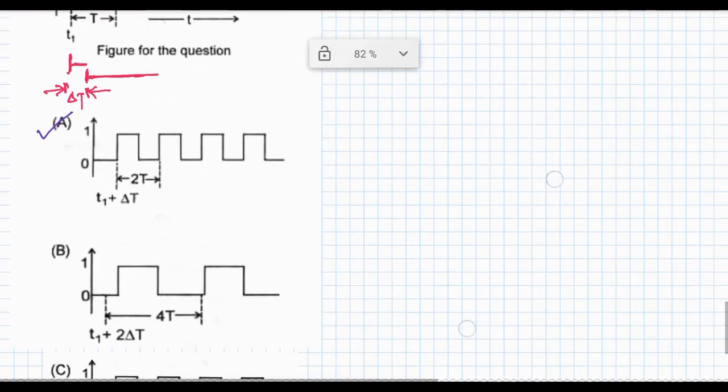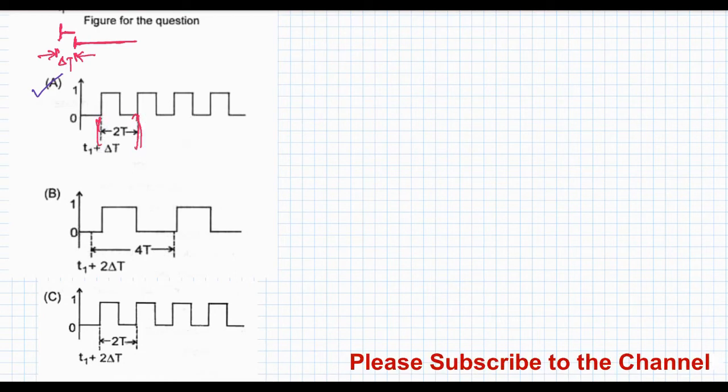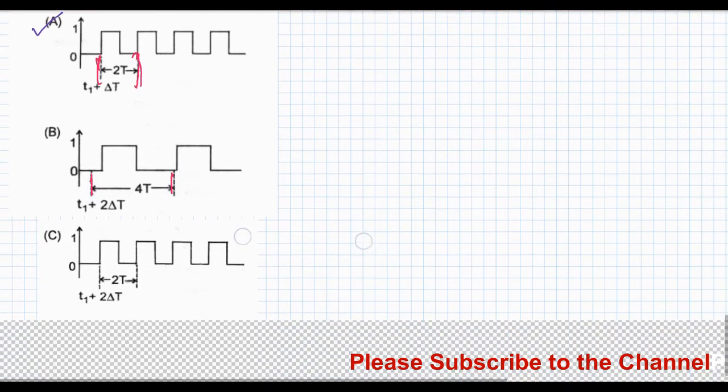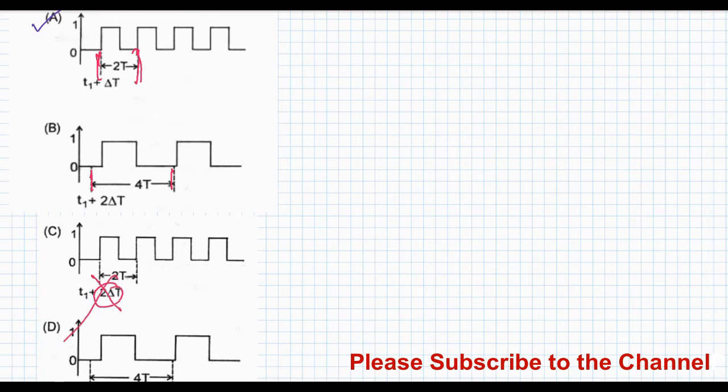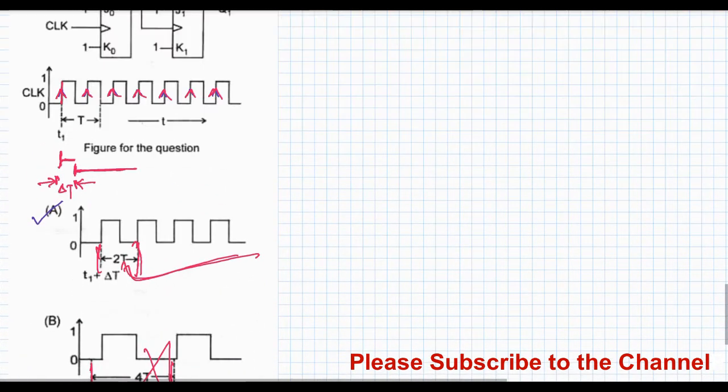Now the options are given. Suppose here the time period is given to be 2t, and here the time period is given to be 4t, but the delay is of 2t. This is not the answer. And here 2t is given; I have already explained why 2t, so this one is correct. 4t is not the answer, and the next one, 4t, is also not the answer. So the propagation delay is t1 plus del t, the time period is 2t, and the frequency will be halved.